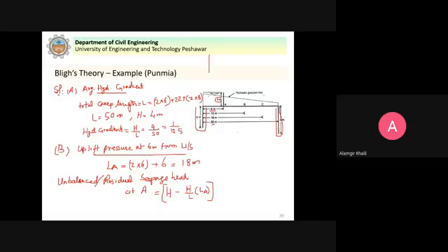See, I explain here. Look, we have this as the total head. So this is H. Now as the water moves, this head is decreasing because of the losses. Let's say this is point A. So at this point there is loss of head. This loss of head we already discussed. This will be H by L multiplied by the creep length up to that point, which is LA. This is the head loss from this H. So what is the unbalanced or remaining? This is the residual remaining or unbalanced.